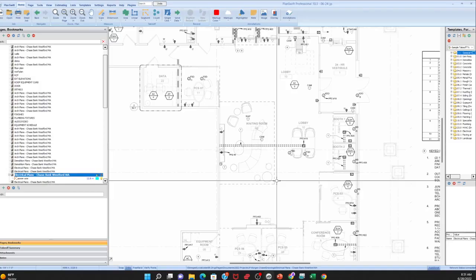But also, if there are things like temporary lighting that's required that aren't necessarily shown on a set of construction documents, or if you need a generator and you happen to miss it in the documents, it'll definitely be mentioned in the specs. That way you won't miss it. So I always recommend reviewing the specifications in detail, take notes, then review the construction documents, take all of your counts, take your measurements, and you'll be ready to roll.